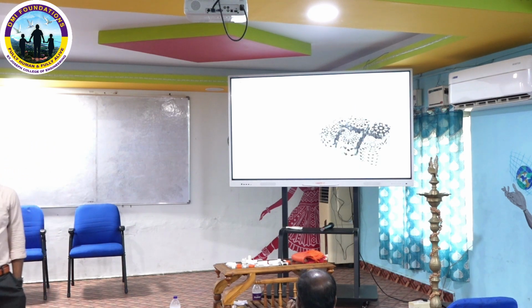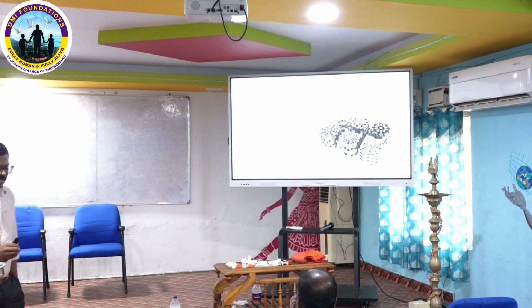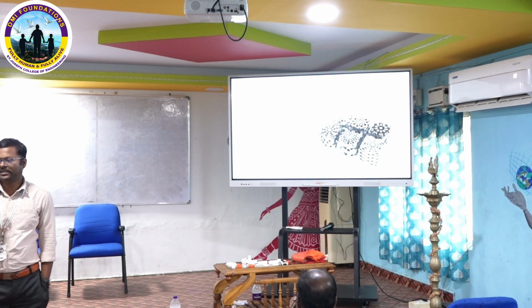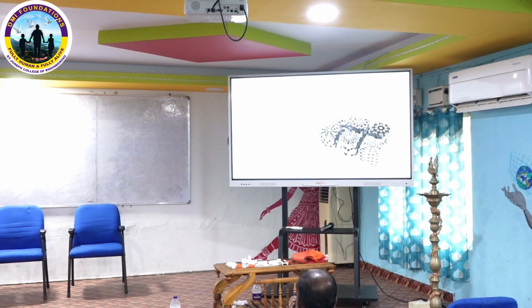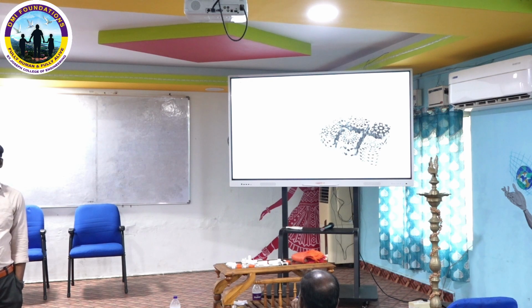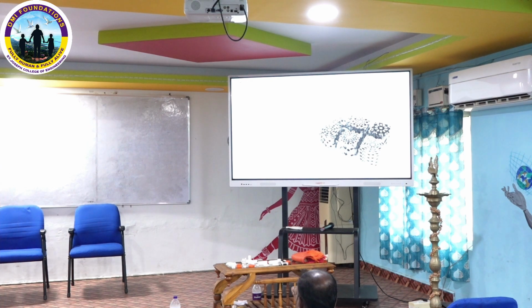First one is concept and objectives. What is that? If I am going to incorporate lattice structures into a component, first of all I need to find my objective. Whether I am going to increase the energy absorption, or reduce the mass or weight of the component, or whether my application is on the thermal side, or I am going to reduce vibration. This kind of objective I have to finalize in the first step.